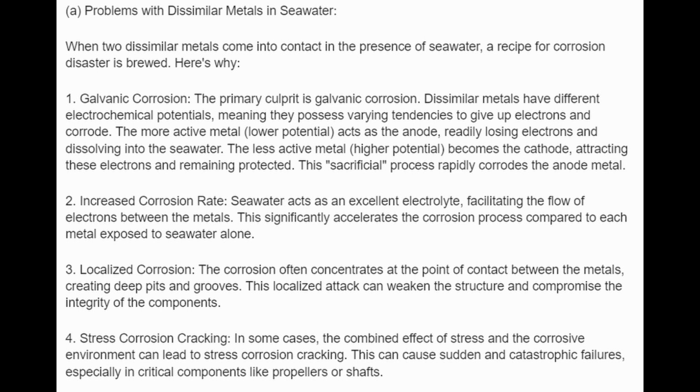Seawater acts as an excellent electrolyte, facilitating the flow of electrons between the metals. This significantly accelerates the corrosion process compared to each metal exposed to seawater alone. 3. Localized corrosion. The corrosion often concentrates at the point of contact between the metals, creating deep pits and grooves. This localized attack can weaken the structure and compromise the integrity of the components.